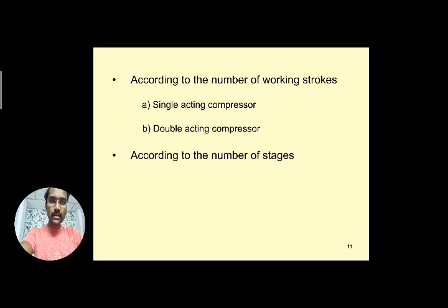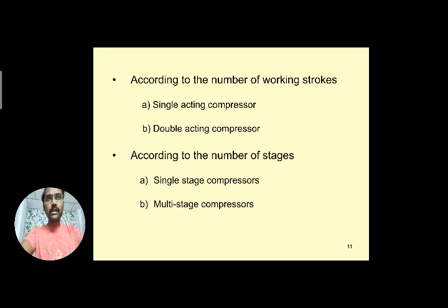Next, the third factor is according to the number of stages. You can take single stage compressors and multi-stage compressors. The compression which happens in a single stage is a single stage compressor, and multi-stage compressors use a number of different stages to attain a particular pressure. So according to the number of stages, single stage and multi-stage compressors. This is the third factor.